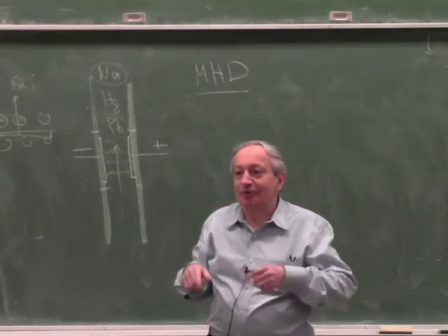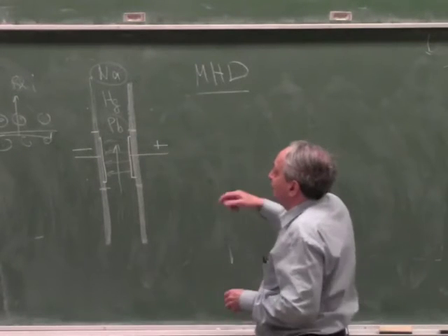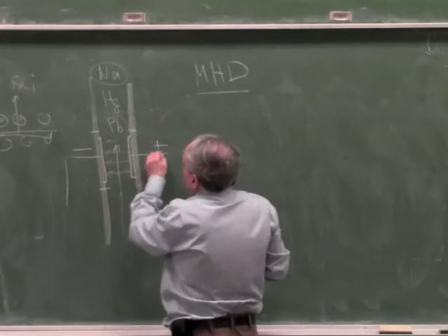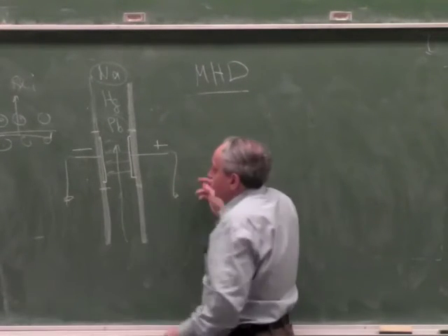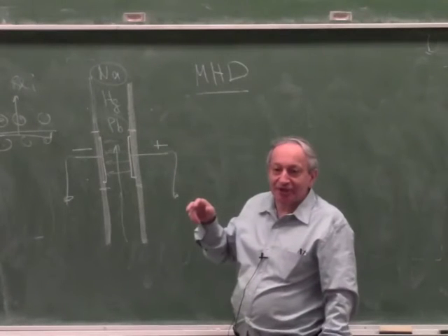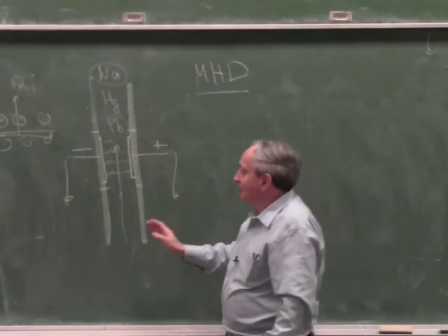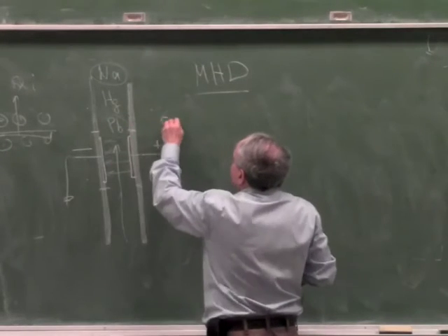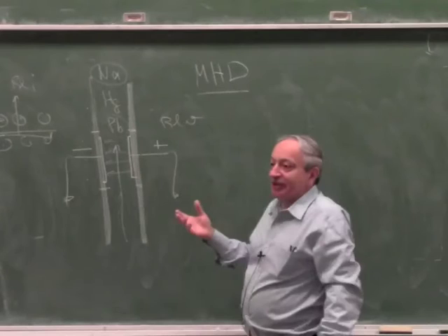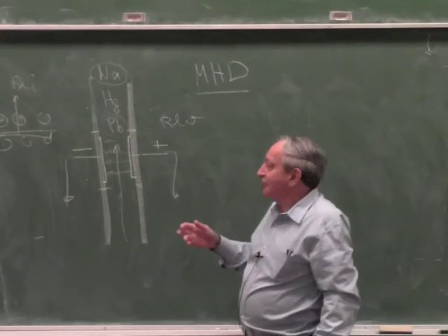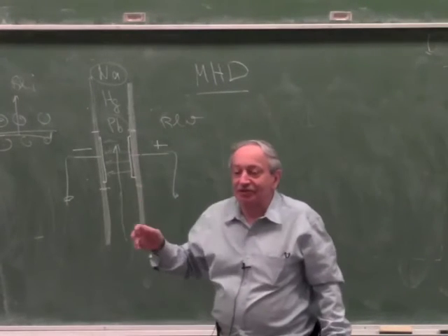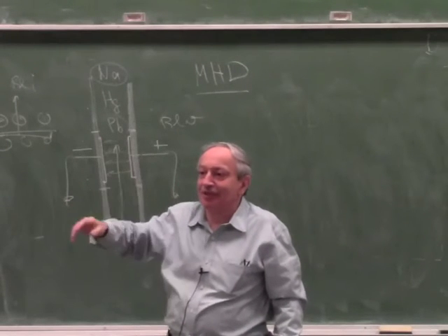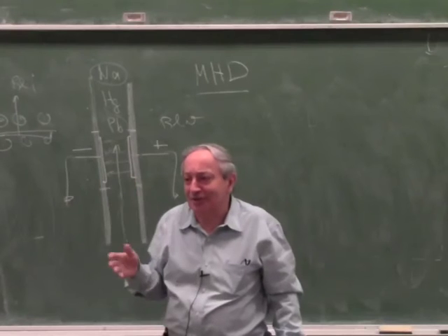Okay? Now let's talk about the opposite. If you fed molten metal and you picked up these two electrodes and looked at what happens without sending a current through it, it will be a generator. Right? Because a conductor flows through a magnetic field, you'll get a voltage, BLV, and that's a generator. So you don't need to run this molten lead through a steam plant and through a turbine, where the steam turns the turbine, and the turbine turns the generator. You don't need all that.